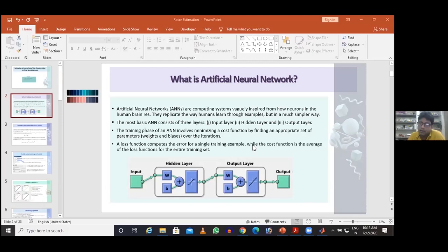It needs a special design to use that separately excited DC machine in such hazardous places. And moreover, it's not maintenance free. Cost is more. So to overcome these things, the induction motor evolved in the market. It is very robust in design, simple in construction, more or less maintenance free, and foremost, it can operate in hazardous environment.